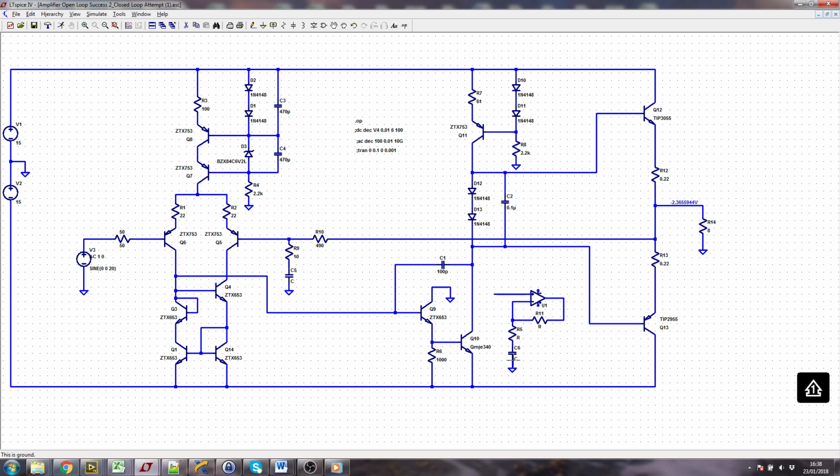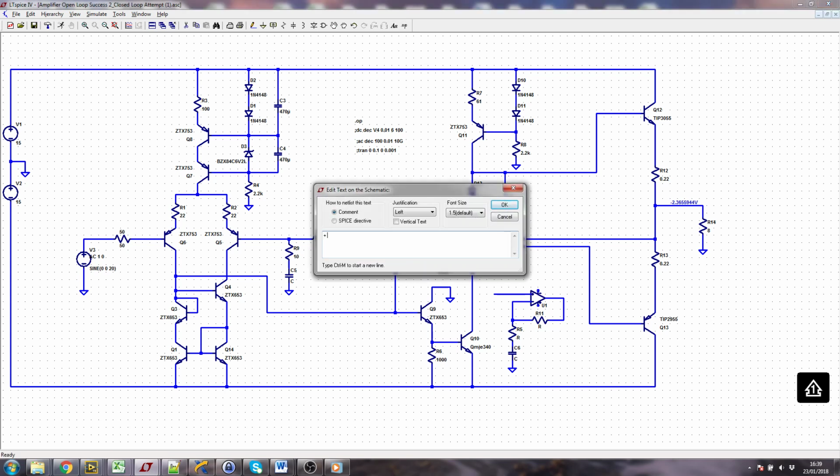We'll have an impedance here of 1 over 2 pi f times C6 plus R5 because they're in series. In other words, this bit will get bigger by the amount of XC6, where XC6 is the impedance of C6 at that particular frequency, 1 over 2 pi f C6. What does that mean? Well, it's 1 plus R11 over R5 plus XC6. So you got, let me write that out. 1, no, that's a plus, let's try again. 1 plus R11 over (R5 plus XC6), I'll put the brackets in.